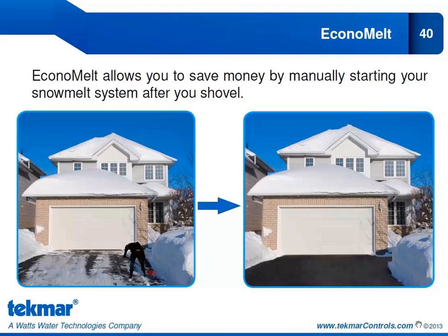So in the system menu, the default for EconoMelt is off. So that means by default you do have the automatic start and the automatic stop. If you change that, so you select EconoMelt on, you no longer have the automatic start. The control will wait for you to manually enable the snowmelt system. However, you still benefit from the automatic stop.